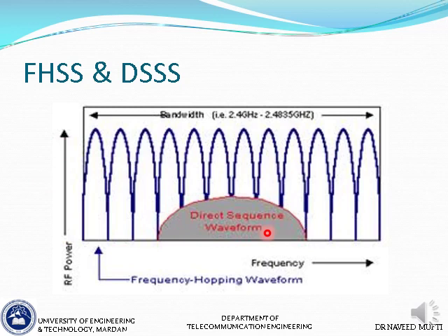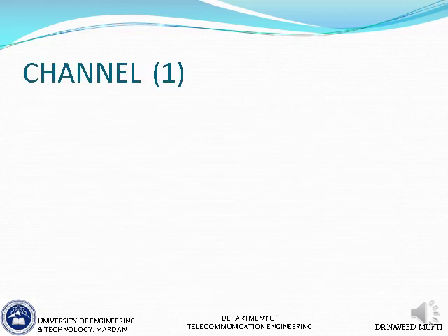So these are the main two types of CDMA, and they're different in their approaches to how they spread the spectrum. So frequency hopping spreads it like this, with individual carriers of a smaller bandwidth but spread over the whole band, where the whole band available is divided into 5 megahertz chunks for the direct sequence, and the whole signal is spread into this 5 megahertz using some spreading code. So that was a comparison of these two techniques.